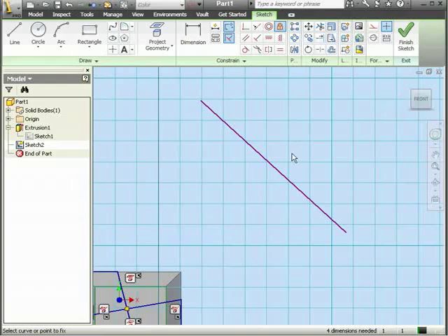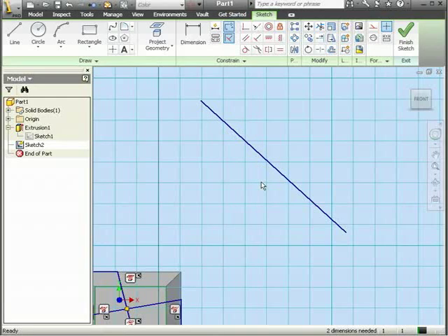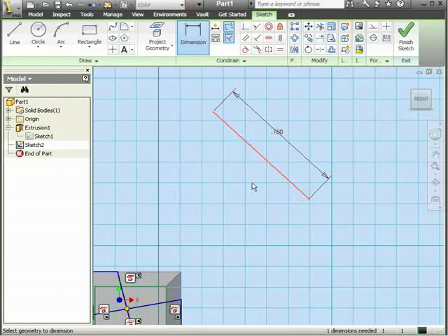Let's select Fixed, and then select the line. Right-click and done. This action has fixed the angle and line direction. The endpoints can still be moved. Let's add some dimensions now. One dimension is needed per the status bar's message. The status bar still tells us that 1 dimension is needed. Right-click and done. I can still move the line.